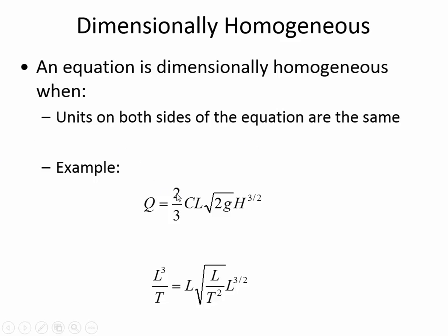We'll look at weirs next semester when we get into hydraulic engineering, but the flow over a weir is dependent on, first of all, 2/3 times c, where c is some energy reduction factor. It's just sort of like a factor that's unitless and related to how much energy is lost as water approaches the obstruction and flows over the edge. But length does have units. Length would be units of meters or feet, depending on what unit system we're putting in.